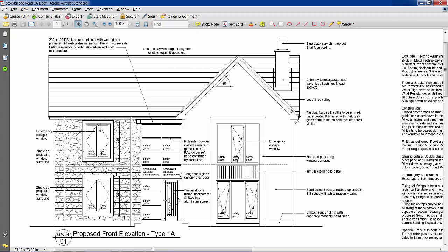And over here, this is a set of double windows that opens out with the hinge on the left hand side and the right hand side. The glass in the middle, this is a glazed system. Notice that these panels here in the middle obscure the floor structure in behind, so that's a spandrel panel. And then the other aspect to a lot of the windows is that you need safety glass when it is below a certain height, so check the building regulations to find out what that height is. And there's also safety glass in the window of the door.